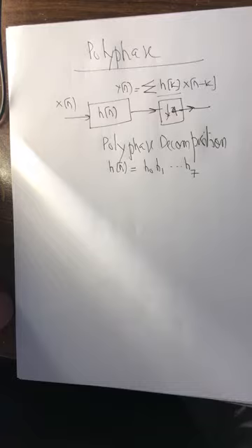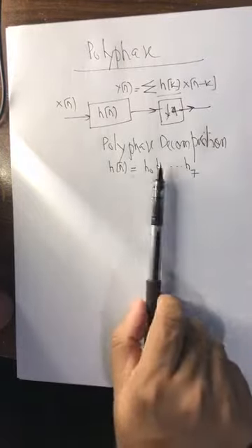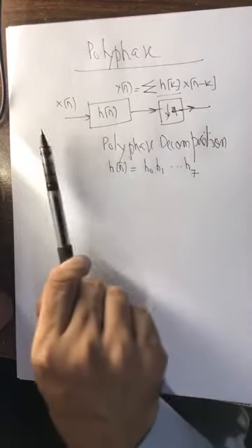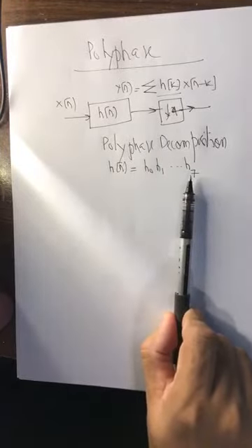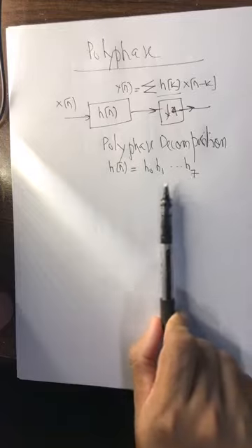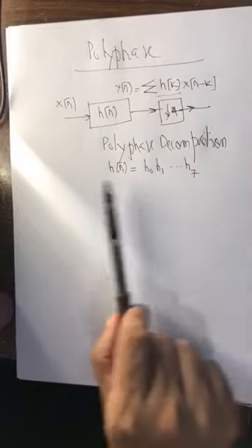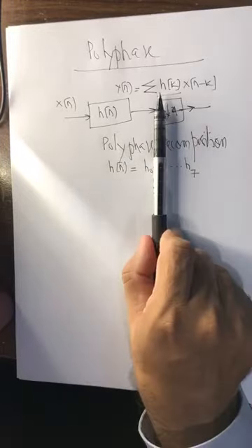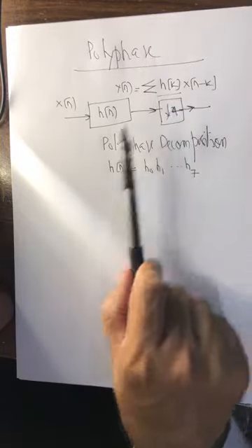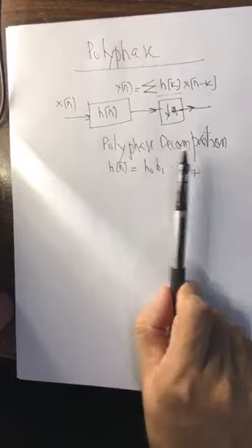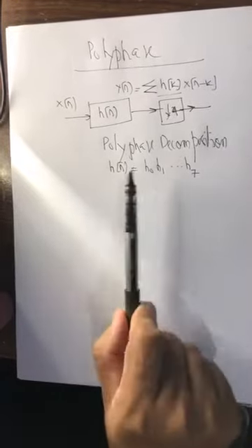Out of every 4 you get 1 sample. But in signal processing, theoretically the way is that first you pass it through this filter. So every convolution operation will require you to do 8 multiplications and 7 additions, and that's what the convolution summation is telling us. And then you keep 1, throw 3, keep 1, throw 3, and that's what you keep doing.